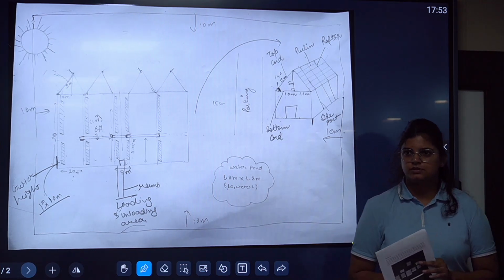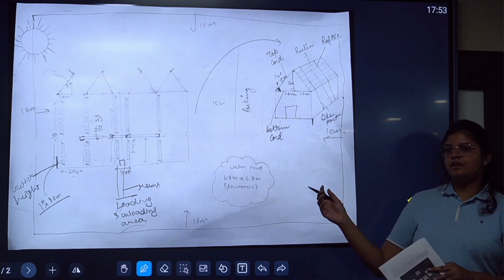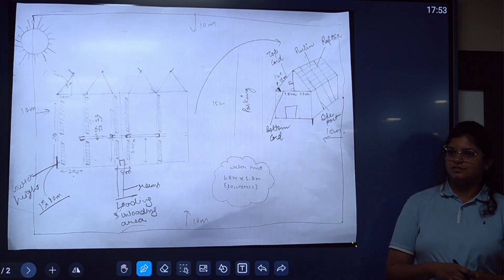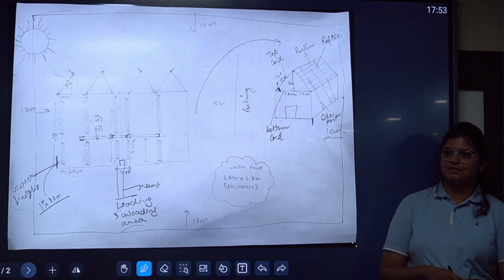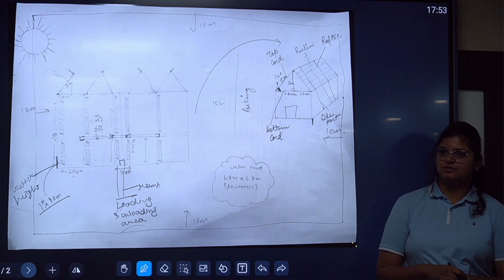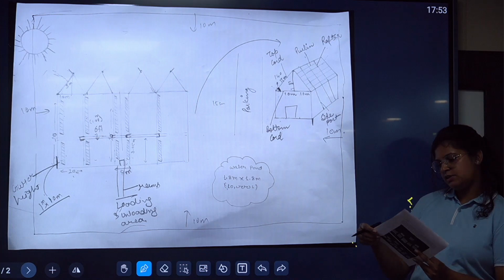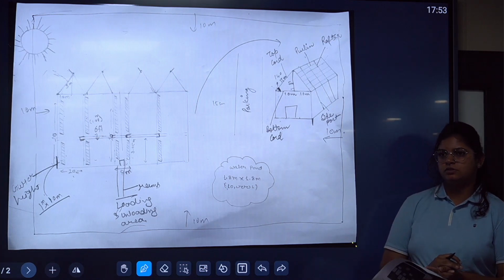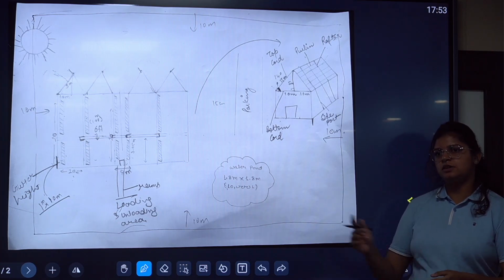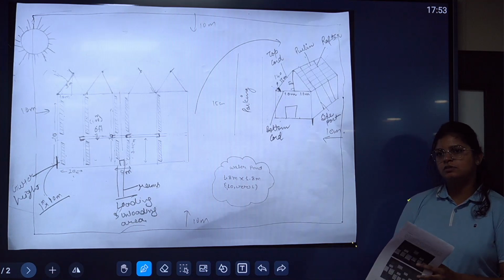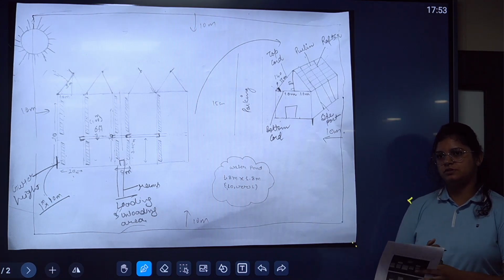Repeat the question, okay? Why is your tank 10,000 liters for a big greenhouse? Sir, 10,000 liters is like a small tank. It should be much larger than that, because you have a multi-span, big greenhouse. I don't remember the area, but it seems like 1600 square meters. That is quite large, almost a third of an acre. So we can increase the capacity or make it 20,000 liters, with 12 feet by 12 feet dimensions for the pond. Right. Double this.